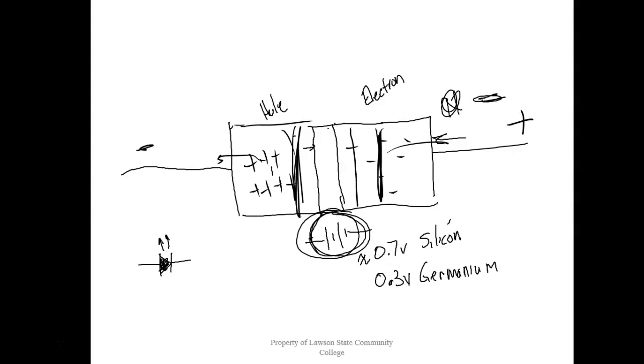So every diode has a breakover voltage, the peak inverse voltage, which is the maximum voltage you can put across it before it blows. So these guys are our check valves. What's a check valve? It only allows flow in one direction. These guys do that.